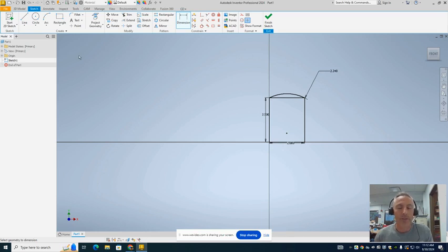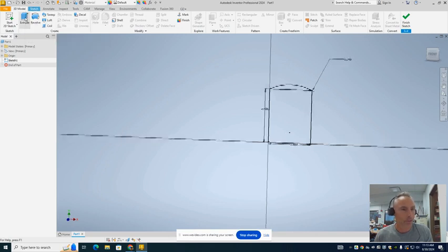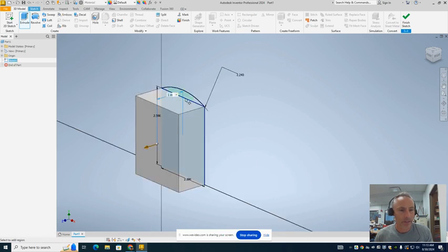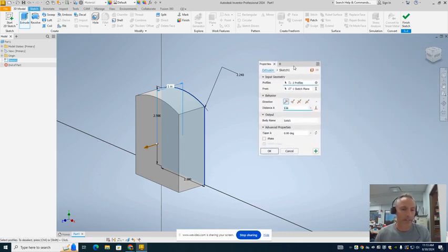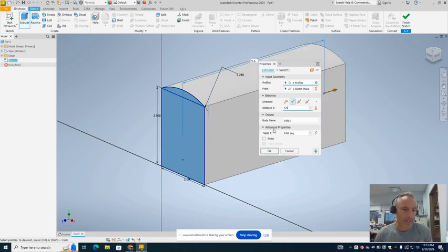At this point, we're ready to extrude to make the main body of the train. So we're going to go to 3D model. When we click on it, one of the options is extrude. We'll click on that, and now we'll get to select that first area and that second area. It really doesn't matter whether we extrude out or in. We're going to have this little box that shows up right here. I'm going to have it extrude back. Again, it's not important. I'm going to have it go 5.5 inches back, and we'll hit OK.